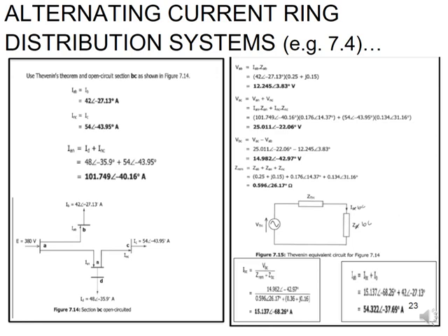Your VBC would simply be your VAC minus my VAB. And then I can say now my Z Thevenin is going to be ZAB plus ZAN plus ZNC, because again, we don't have an impedance going from N to D.